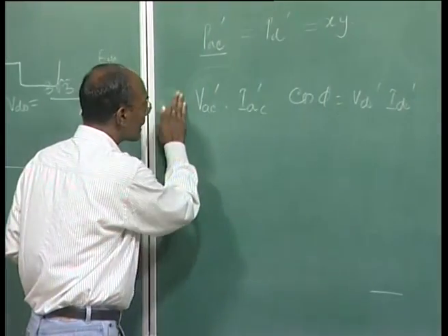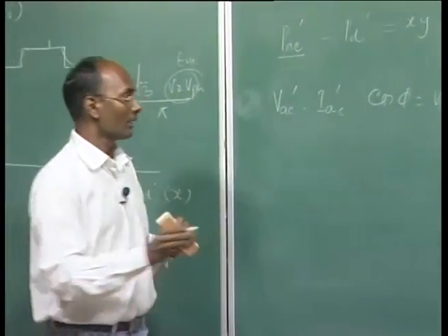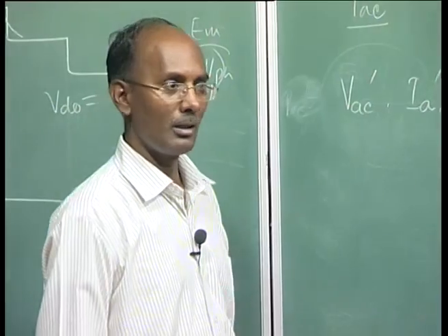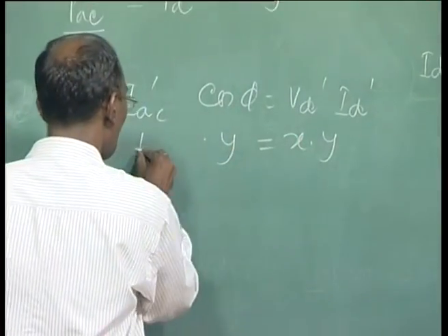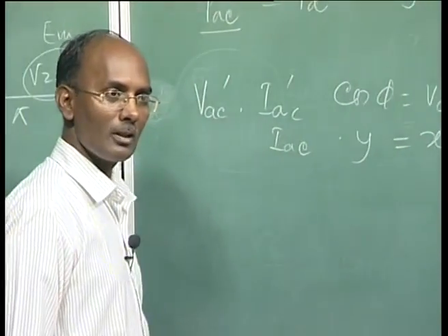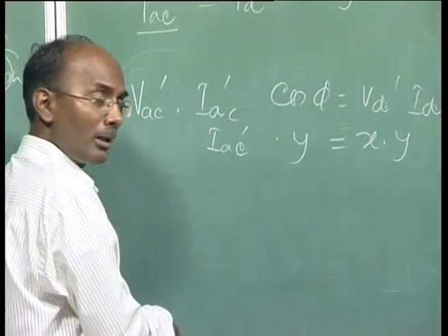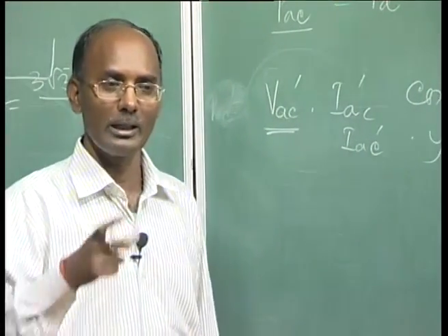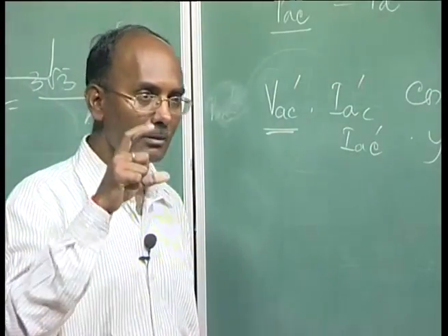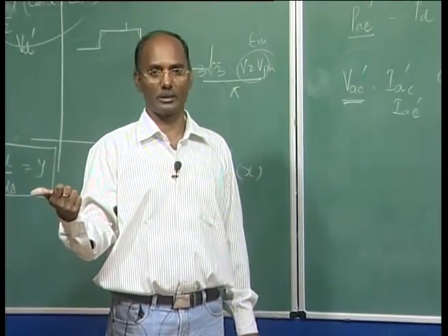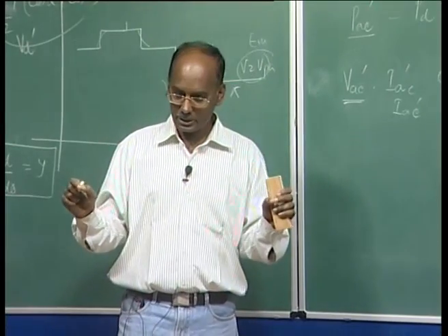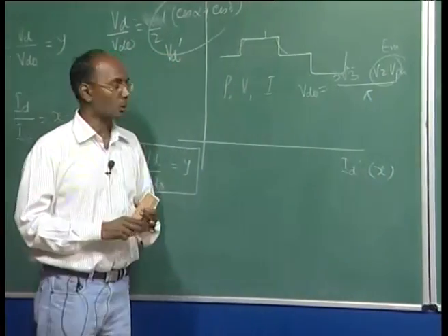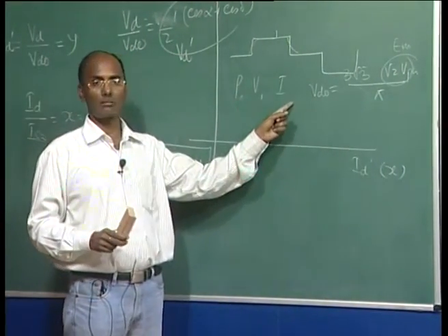So here now I am writing this value, so there is no question. Now this value is your X into Y. This is also your Y, IAC prime here, and this value is the voltage base, and this voltage base is basically given. Your power base and the voltage base are assigned, then your current base is calculated. In any per unit quantities, there are basically three quantities: power, voltage and current. Two are dependent, and one is automatically calculated.